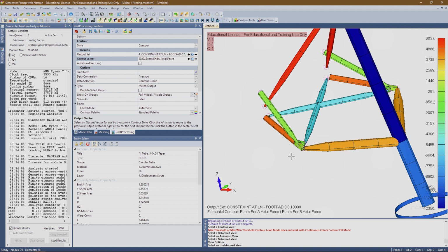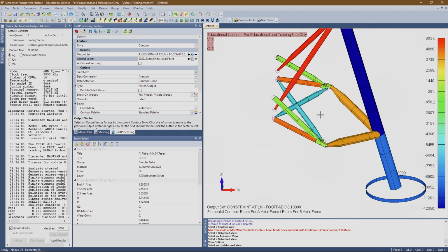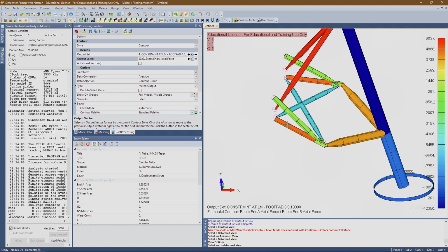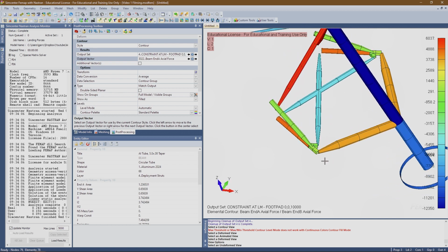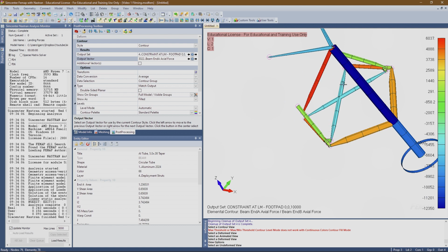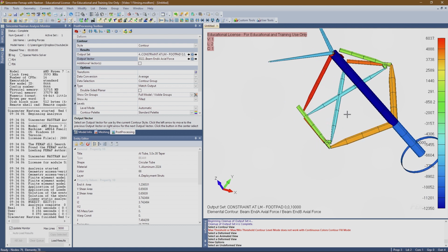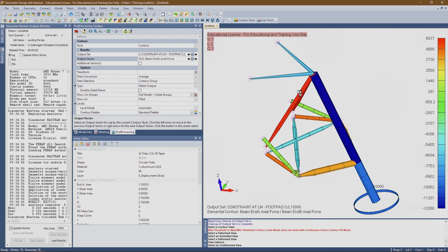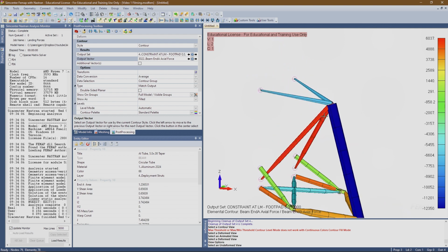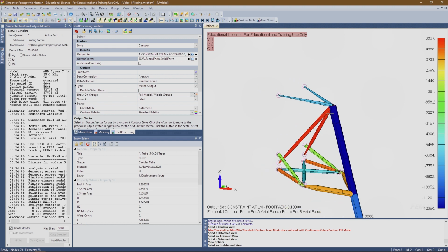And so this inward force is being reacted out by the cross beam here. And then this guy is in tension. Again, that makes sense because this guy is in tension, right? So it makes sense that they're both in tension, and this is in compression to keep that from collapsing in on itself. So hopefully that all makes sense. And then outrigger here, right, it's being pushed up. So the bottom struts are in tension and the top struts are in compression, which totally checks out.